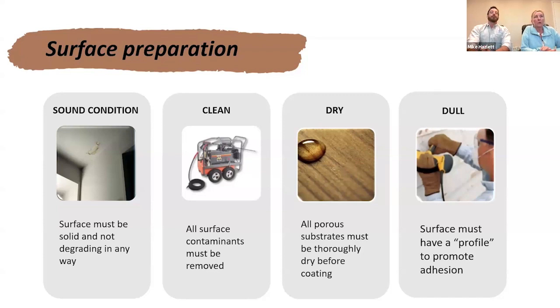One of the questions we always pose when we go out and they say, well, we've had a problem, we've had moisture, is trying to investigate what happened, whether there was improper surface prep or some other underlying issue when we get called out to a complaint. Can you guess what percentage of coating failures can be directly attributed to inadequate surface prep? The answer is 80%.